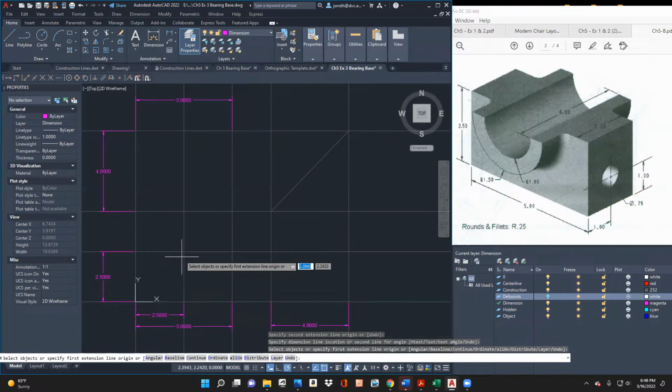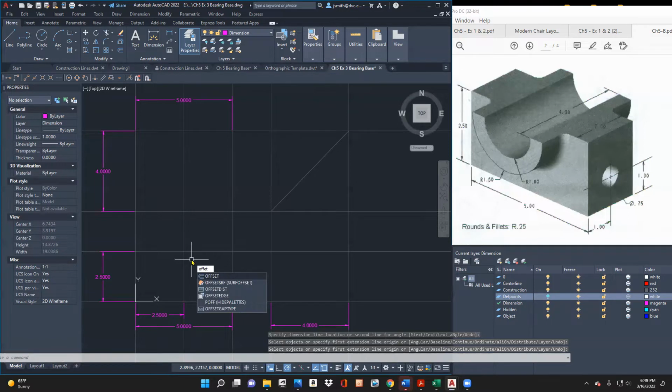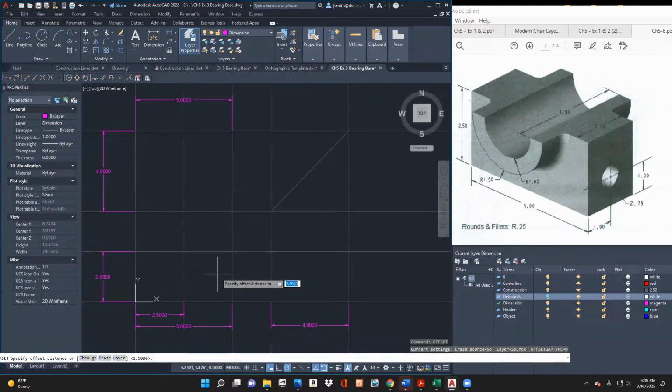Okay, so that'll make it easier for me because then I can draw my U shape. So let's go ahead in the center. I could go to the layer and do it, but let's go ahead and do the construction. So we'll then say offset. And it's telling us that the radius is 1 inch. So the distance is going to be 1 inch. I'll type in 1. Select the center of this line and move it over here. Push enter twice, 3 times.